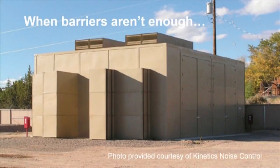they add pressure drop. In most cases, the fans supplied with HVAC equipment are sized for the pressure drop of the coils. Additional pressure drop reduces flow and may overload the fan motors. Of course, all this should be done in coordination with the equipment manufacturer and an acoustical consultant. The solution in these extreme cases is to duct the air in and out of the box using additional fans and duct silencers. The fans can be sized for the pressure drop of the silencers. In some designs, the original propeller fans on the unit are removed, and in other cases, they stay in place. It's not an easy fix.